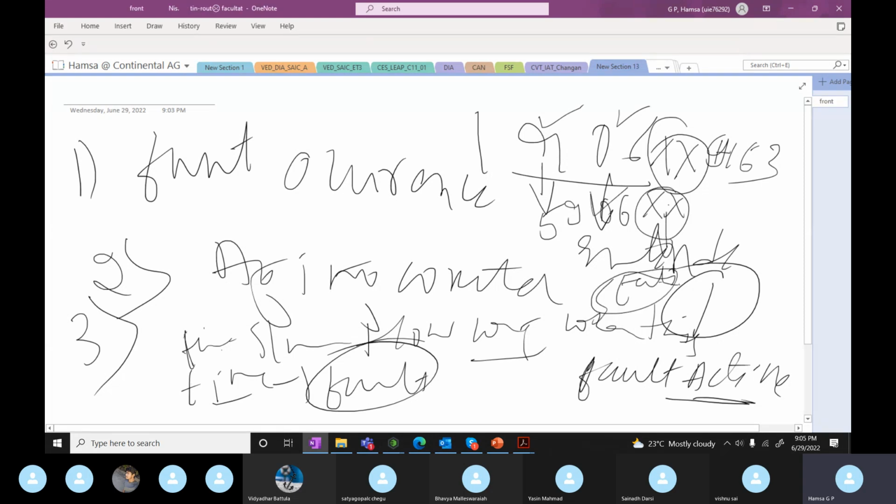So 5906 and also the extended information like fault occurrence. Fault occurrence means how many times this fault has occurred in the system. Another is how much time was taken by the system to set this particular DTC. And the aging counter. What does aging counter mean? It is the age of the fault, how old the fault is.